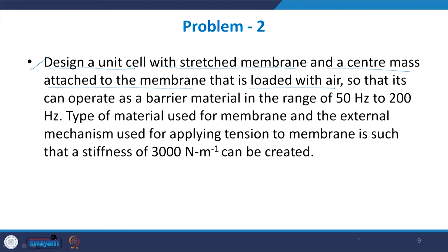So, we have to design this particular unit cell type 2 loaded with air so that this unit cell can act as a barrier material in the range of 50 to 200 hertz. So, we are designing it so that it can act as a perfect barrier material and it can block the sounds between 50 to 200 hertz.